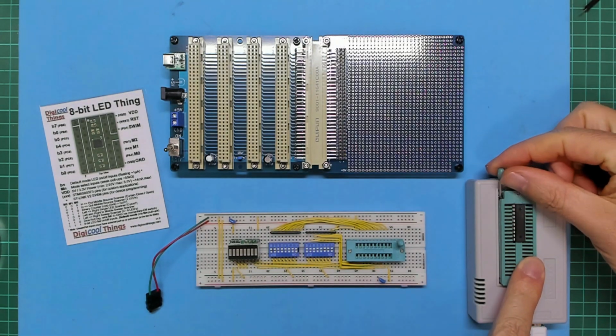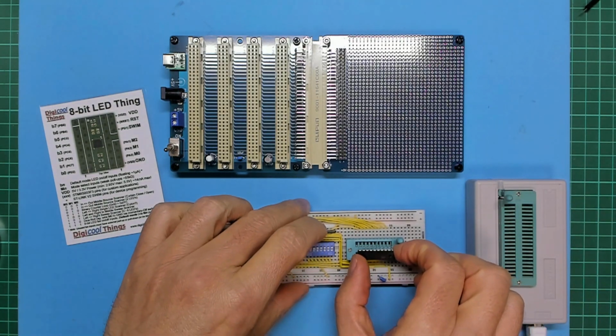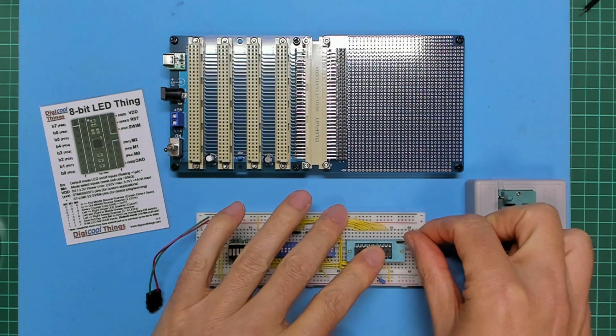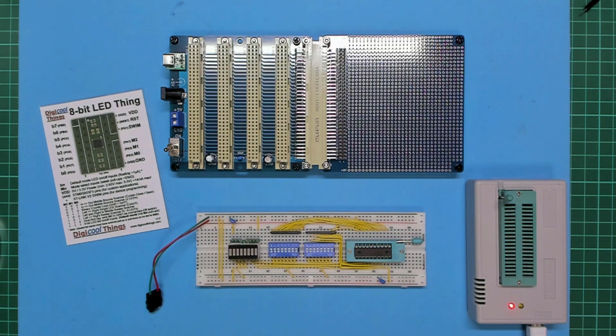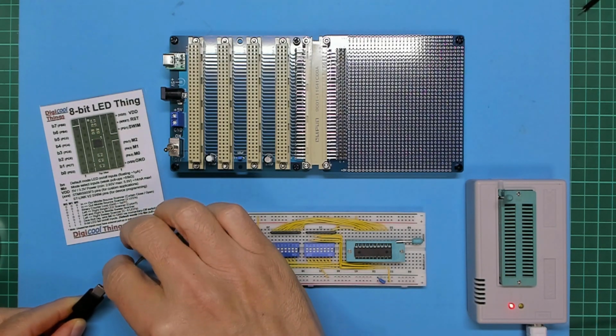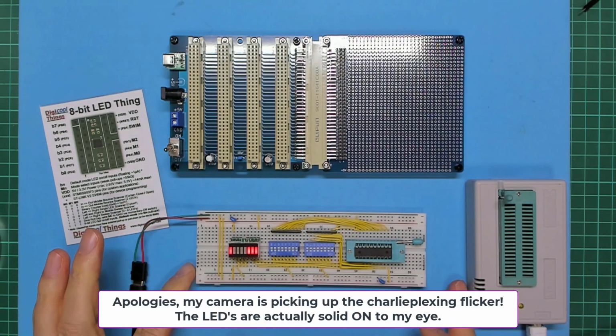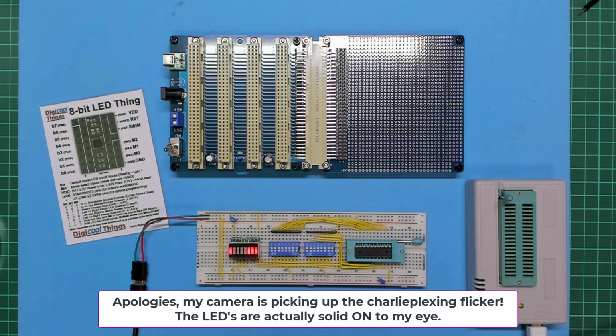So let's take the PLD chip out of the programmer, and we'll just move it across to the ZIF socket on the breadboard. Lock that in place. And we'll power up the board. So I've got my USB-C power. Plug that in, and initially you can see, with all the switches off, effectively all of our 15 inputs are pulled high. We can see the 3 output LEDs are all high, the LEDs are on.